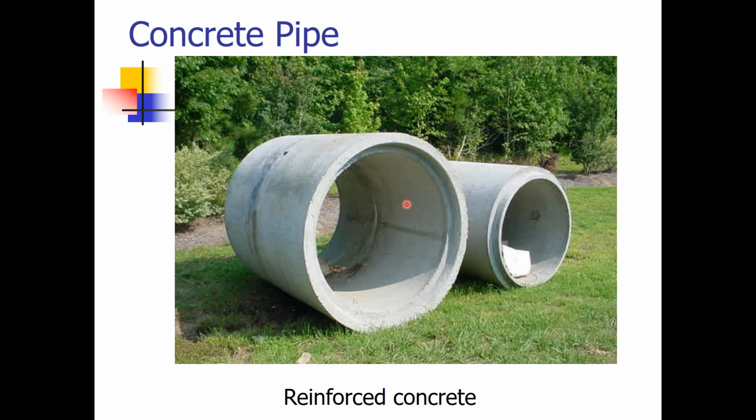If you're using the round concrete pipe, if it's reinforced, you want to make sure when you put the two pieces together, as you can see here, that there are no cracks and no issues. Now, especially when working with these with heavy equipment, these things get banged, they get bumped, they get dropped, they get cracked, and all of a sudden we have a water infiltration issue in these.